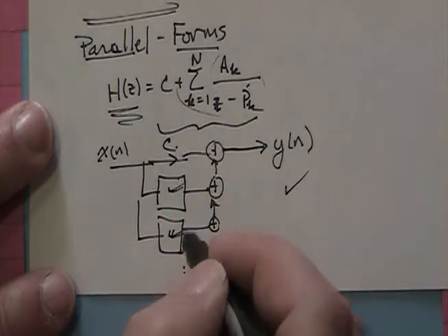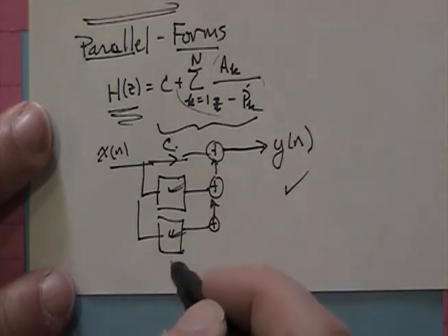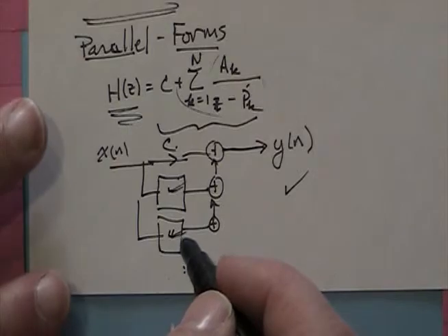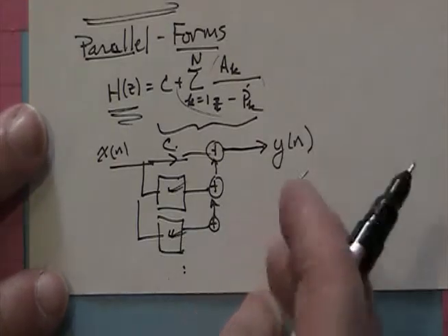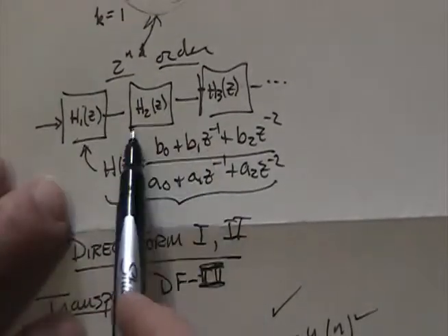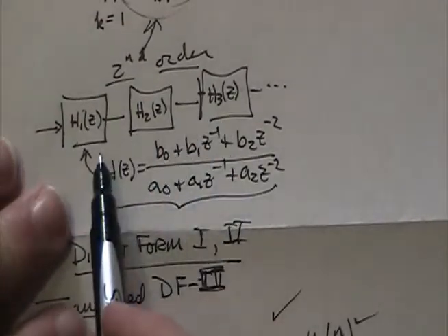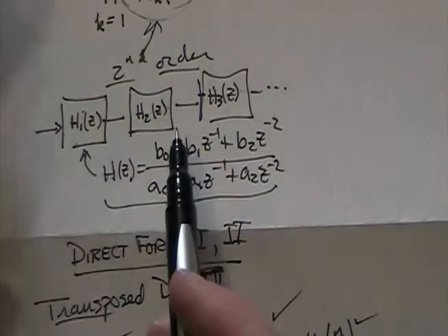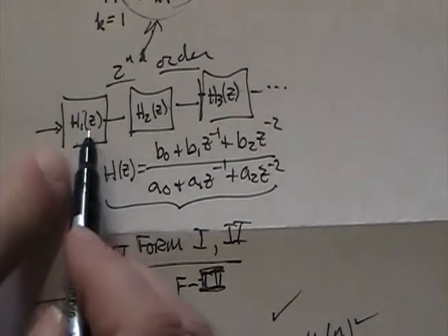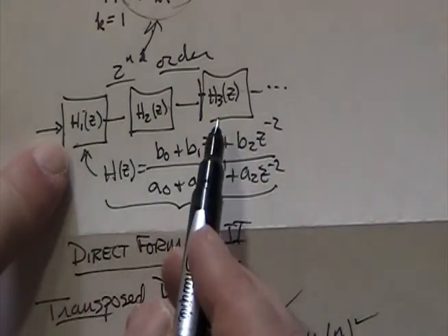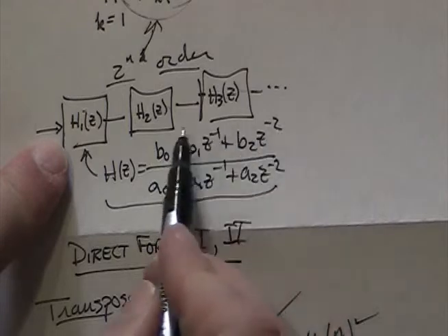It has some computational efficiencies if I can offload these calculations among different processors. And some disadvantages, so the cascade representations tend to be much more common, particularly where I'm talking about a filter that's selecting a band of frequencies. If I'm trying to reject frequencies that are not desired, these zeros end up being important.